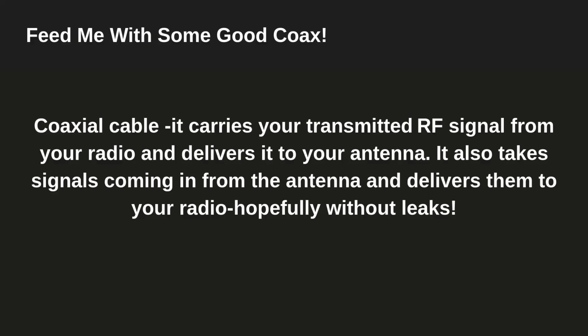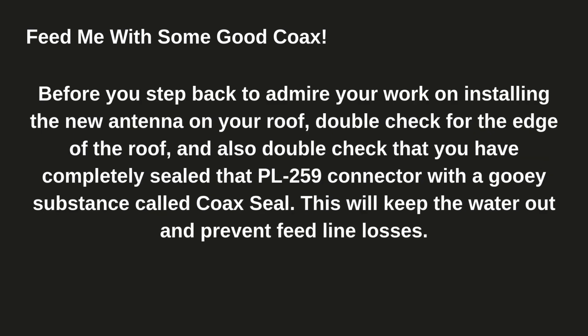Coax cable carries your transmitted RF signals from your radio and delivers them to your antenna. It also takes signals coming in from the antenna and delivers them to your radio, hopefully without leaks. When you install your new antenna on your roof, double check the edge of the roof, and make sure you have completely sealed that PL259 connector with a gooey substance called coax seal.